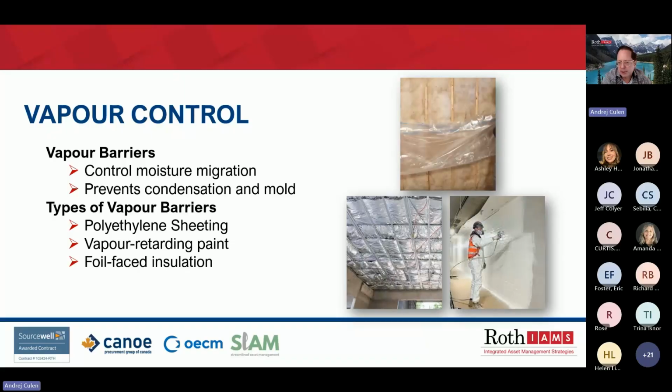The anticipated vapor condition and building codes determine whether you will need a vapor impermeable or a vapor permeable air barrier. However, the complicated nature of this decision often requires a building engineer to decide the best air barrier for your project.